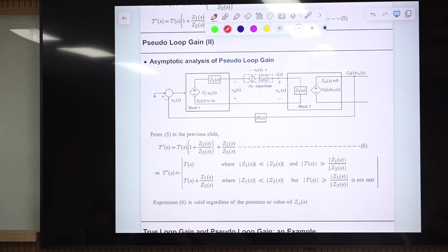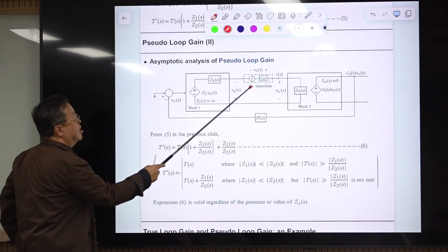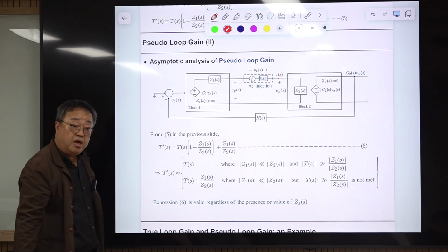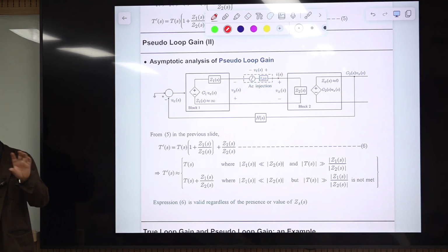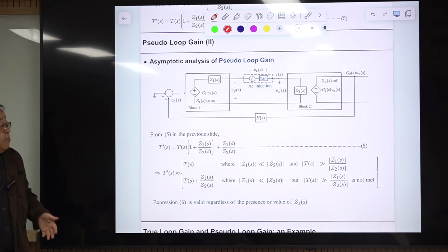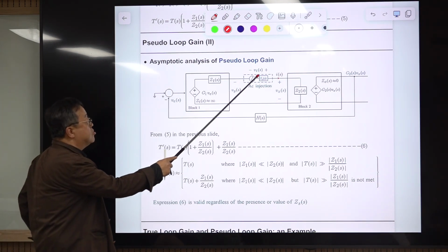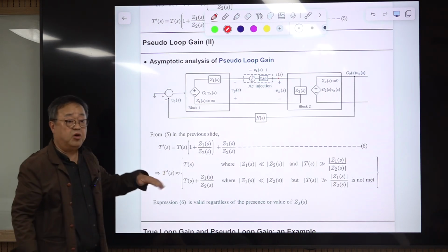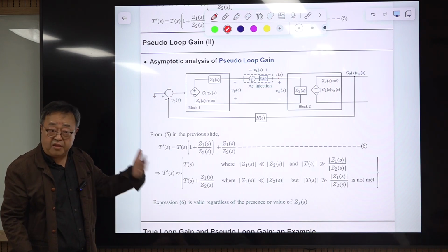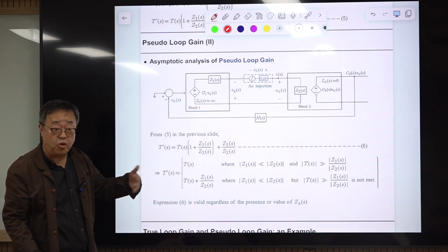So this is the method, and we are inserting this voltage source. This is called voltage source insertion. There is another way of measuring this loop gain. Maybe you insert a current source, a current disturbance, in parallel with this. For some cases, that approach has some advantage.